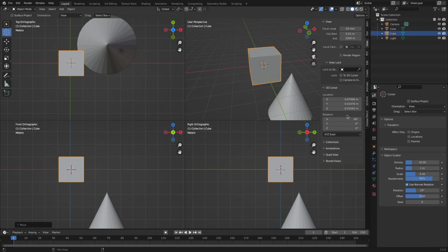So if we really wanted to be meticulous about where the cursor is, we could simply Shift select. Right, you remember how to do that? Hold Shift down while you're hovering over one of the text area bodies, then drag down across all of your fields. And now whatever you enter will be entered into all of them. Hit enter, and now we are zeroed out. It is directly set at the origin of our entire three-dimensional landscape here.